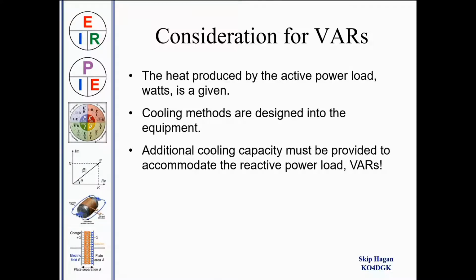So you may have 10 watts of output power, but along with that, there is some reactive power component that also produces heat. So the designer of the equipment must consider VARS in addition to watts to provide sufficient cooling to prevent damage to the equipment.